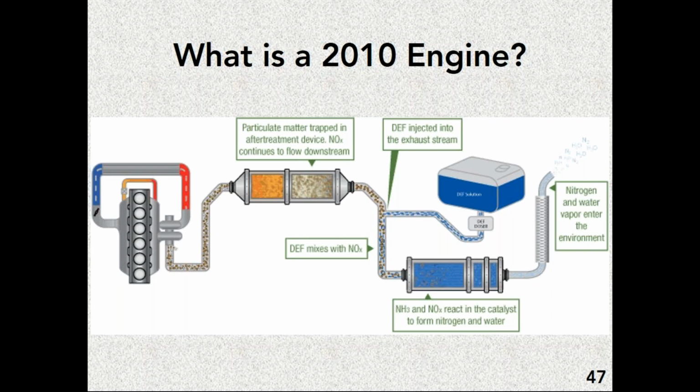A lot of people confuse the idea that the filtration system and the SCR system are connected somehow. They are not. They're different systems, completely different systems. They do completely different things in completely different ways. They just happen to be on the same engine. So when I hear people say the DEF fluid is going into the filter, it drives me nuts because it does not go into the filter. It's specifically for the SCR system.